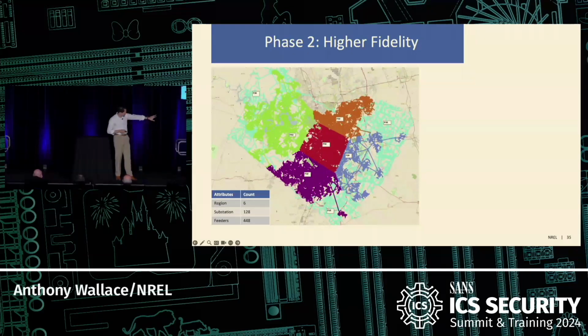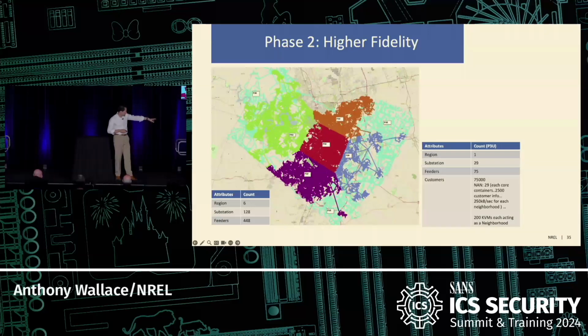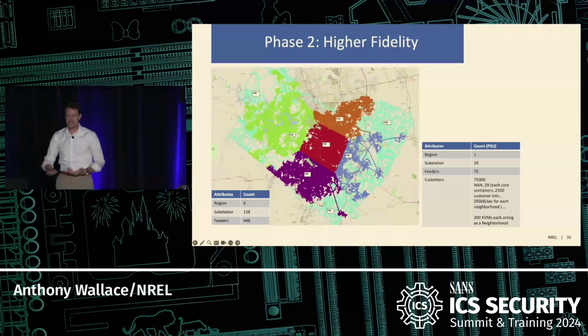And we were able to model this purple region here, which has approximately, it's really more like 78,000 loads, commercial and residential in this area. And OpenDSS represented almost 30 substations throughout this distro. We had 2 fictitious distribution companies with a transmission company sitting on top of that. Again, we use PowerWorld for the transmission. Travis County, which is the county that Austin sits in for that particular model.